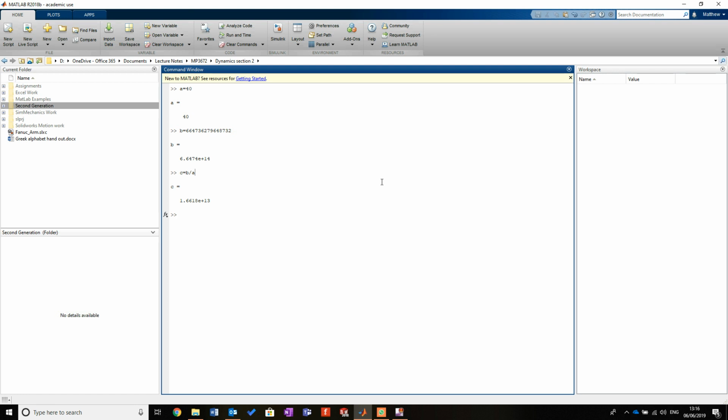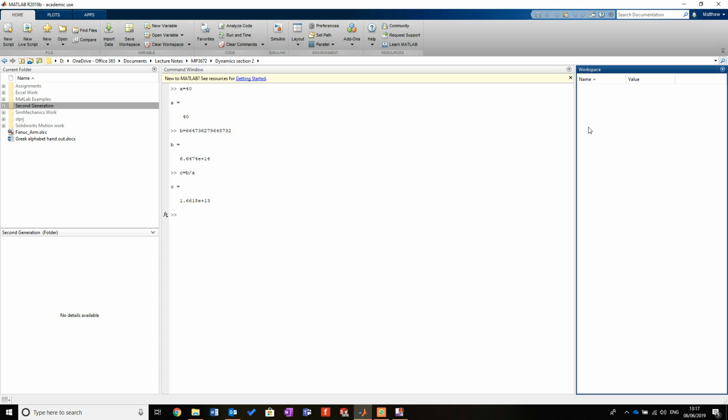Say you're running a simulation, and every time you run it, for some reason, it just keeps dying. No idea why. What can actually happen is, if we run a script, if we run MATLAB, anything like that, it will be storing these variables here. So if it's vital for you to start a simulation with a predefined variable, it looks and says, oh no, it's alright, you've got it in the workspace. And then it will lead to your simulation messing up. Trust me, I've done it many years before, and many moments of screaming and shouting and lots of harsh words.